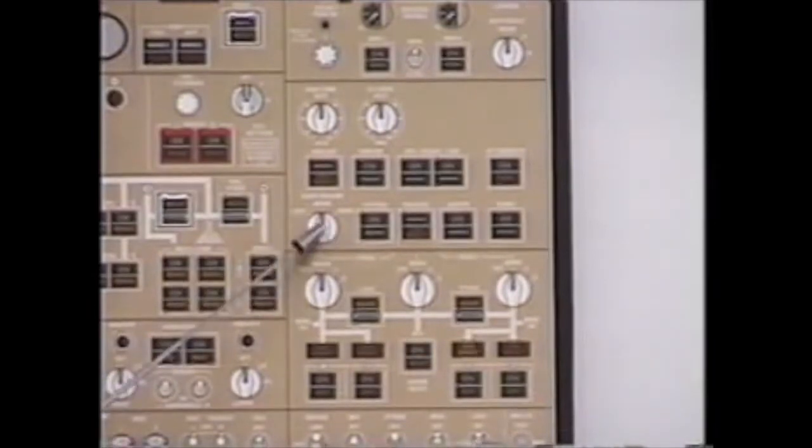Continuing our discussion with equipment cooling. Equipment cooling draws cabin air into the E&E racks downstairs below the first class and discharges that equipment cooling air one of two places, back inside the lower cargo compartment or overboard, depending on the outside air temp. With the selector in normal, we're on the ground at the gate, engine shut down, outside air temp less than 45 degrees, the equipment cooling air will be discharged into the forward cargo compartment. Temperature greater than 45 degrees, it'll be discharged overboard.